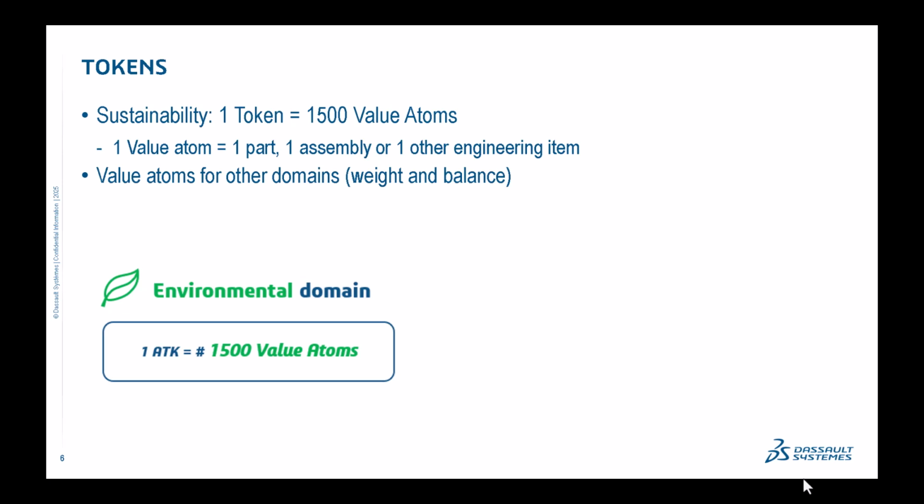When performing lifecycle assessment on the 3DEXPERIENCE platform, data science tokens are licensing items that are consumed when you add lifecycle assessment information to an engineering item. In this case, an engineering item will refer to a part or assembly created in SOLIDWORKS. In the environmental domain, a single data science token is divided into 1,500 value atoms.